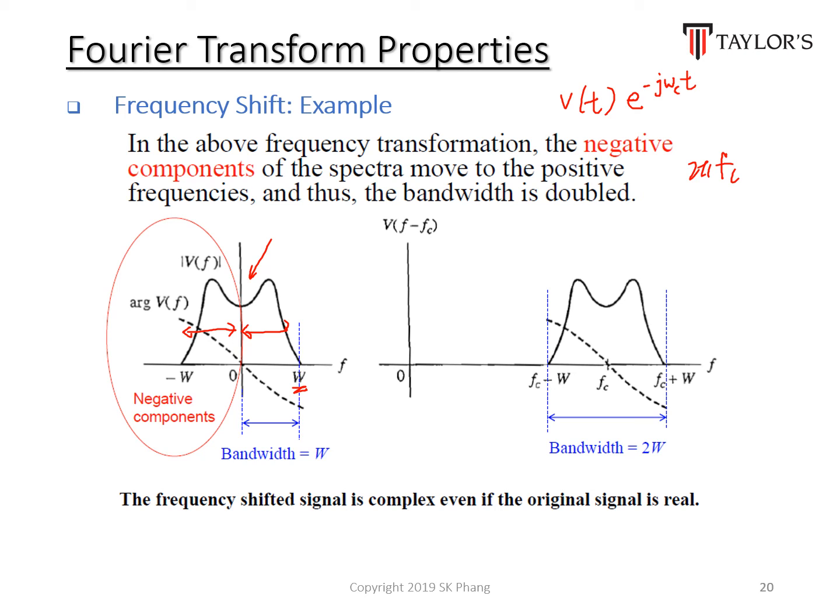And then when we do the Fourier transform of it, we'll get exactly the same shape in terms of frequency response, but now it is shifted away from zero. So if you draw it, extend it on the negative side, you will also see the same thing on the negative side. But now we can ignore the things on the negative side, because with this itself, we are able to reconstruct back our original signal easily.